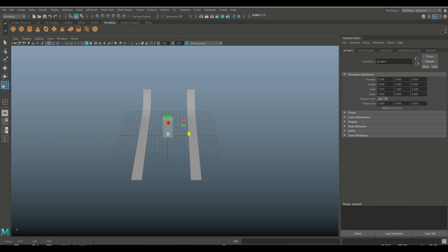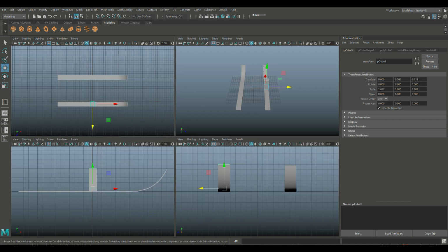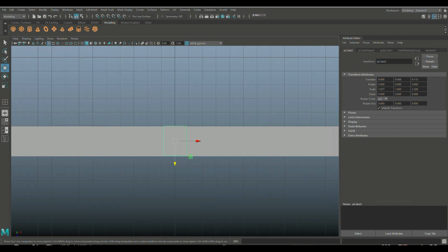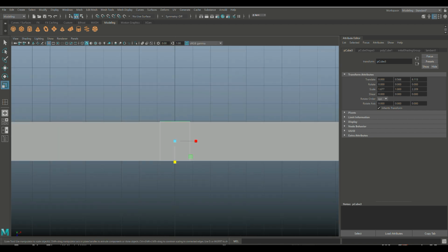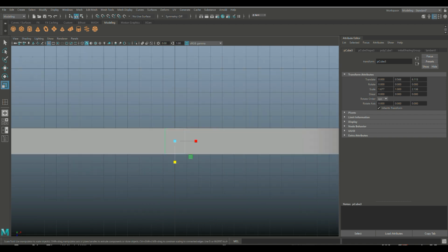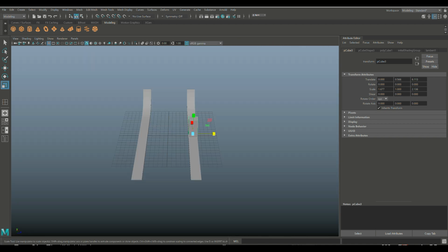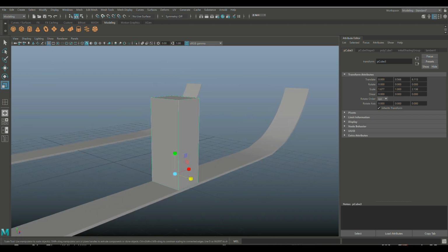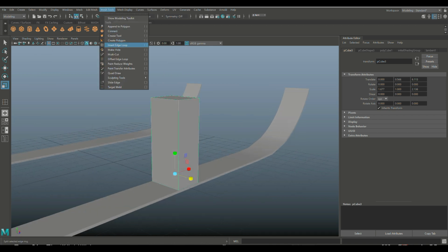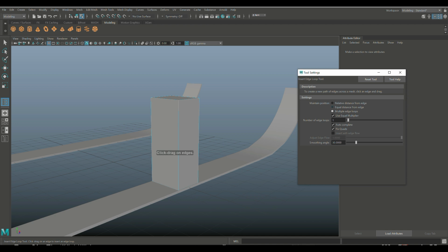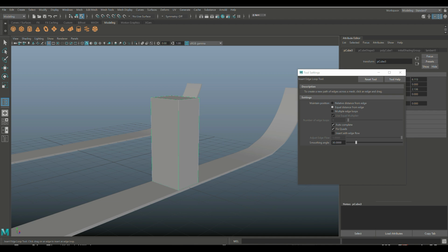And what we're going to do is we're going to position that on one of these guys, like so. Make sure it's a good fit. Have to frame that. Hard to bring it in, just a little, right? Then we're going to go in here, after frame again. Let's go to Insert Edgeloop, option box. Let's set that to single, right? So we can go in here and put one in here. Let's see, we'll do one about there.